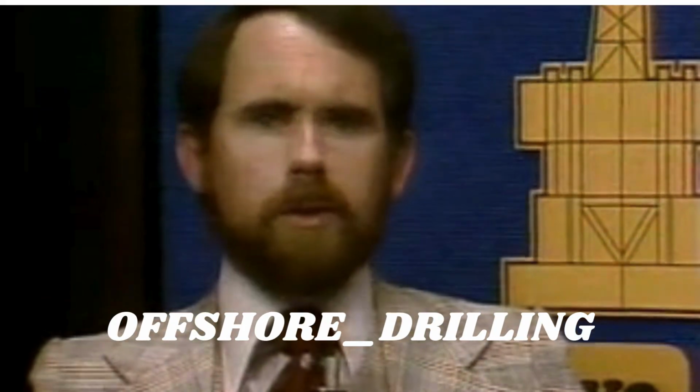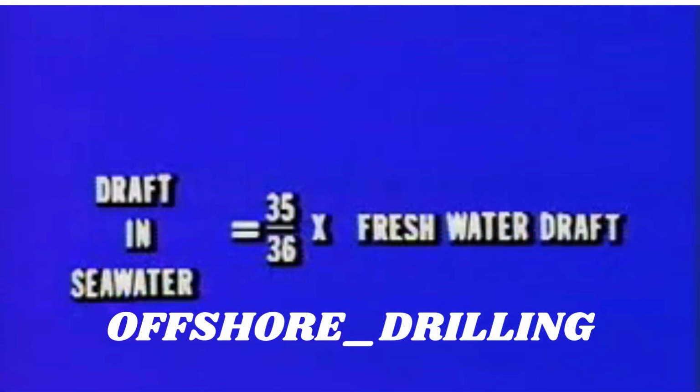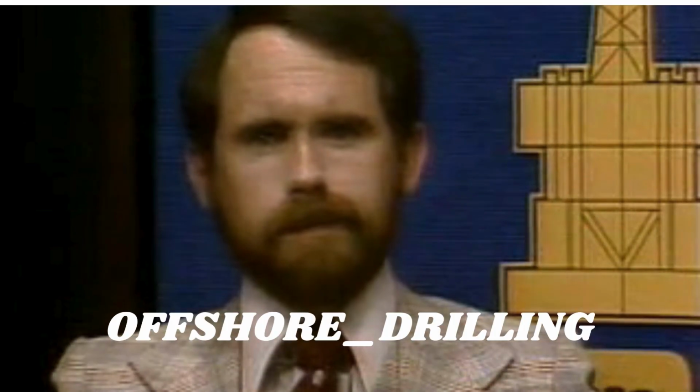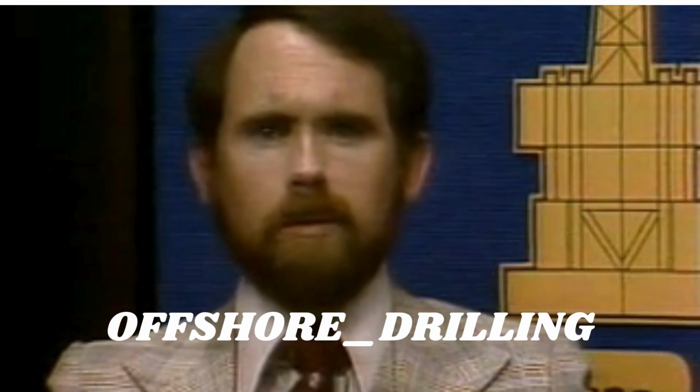The formula for solving this problem is: the draft in seawater is equal to 35 over 36 times the freshwater draft. So multiplying 48 feet freshwater draft by 35 and then dividing by 36, we get a result of 46 feet 8 inches, which is the seawater draft. The ship has changed draft by more than 1 foot.